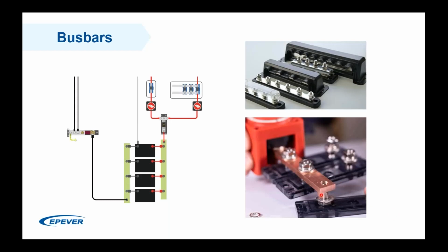So if you take these two, you will get the area. If you multiply the width by the height, depending on what you name it, then you will get the area that current can flow through, and it's the same as the cable sizing. And of course, it's recommended to shield the copper bars.